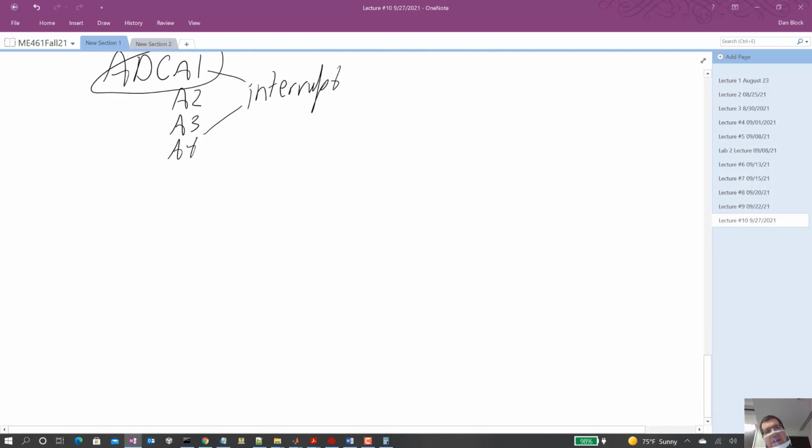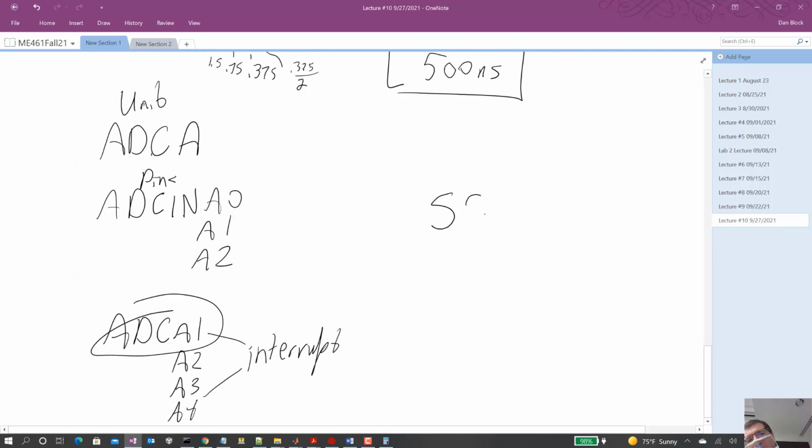Anyway, finally, in each of these ADCs, there are things called start of conversions, SOC. And there's SOC 0 through SOC 15. This is what I've got to talk about first thing next time. You associate a pin with a start of conversion. And this is what tells the sequencer, okay, sample this pin first. SOC 0 is always going to be, for us, the thing that samples first. Then SOC 1, then SOC 2, then 3. And then it goes back to 0 and does it again whenever you're ready to do it again.